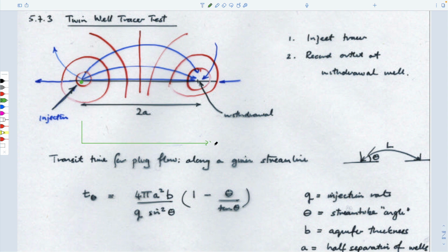And so if we plotted in X, well, it could be a water table, I guess. You could think of it as a water table or a pressure, same thing. This could be the water table, or this could be a pressure gradient, because we know that advective velocity is equal to k over mu porosity dP dx, right? Higher pressure here, lower pressure there, drives flow.